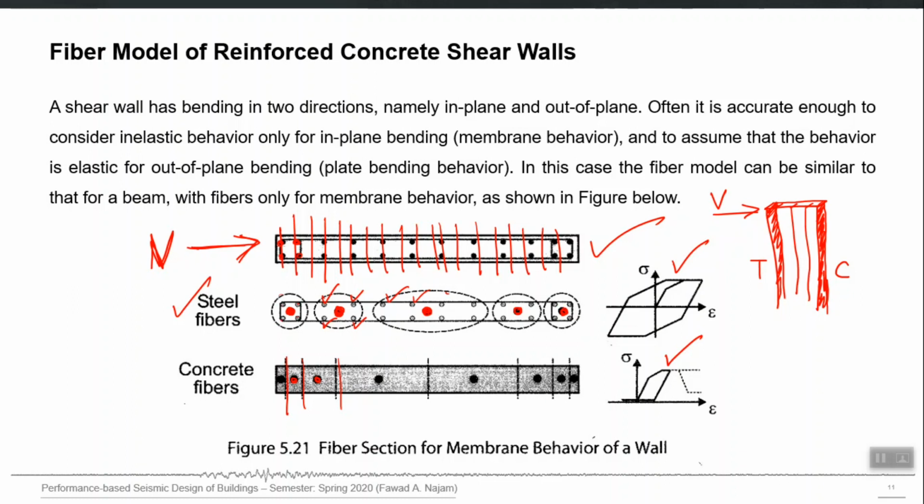We should always keep in mind that whenever you assign a ductile plastic hinge to any location, it is understood or well established that the real structure will be able to develop those plastic rotations. It is confined enough to have and handle those kinds of rotations, right? So the real behavior should be given as an input to the plastic hinges. So once you follow ASCE 41, you should make sure that the ASCE 41 curve is actually exhibited by the real structure at that particular location, right?